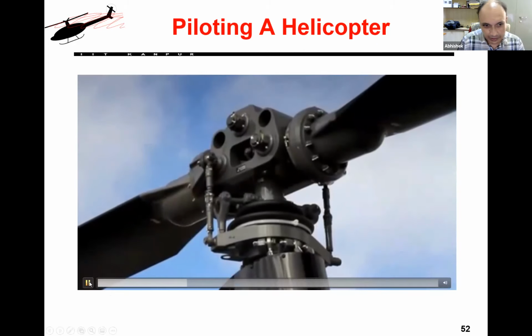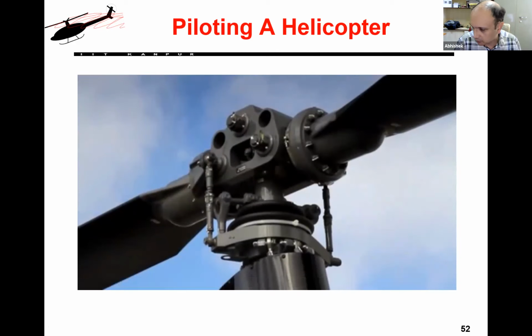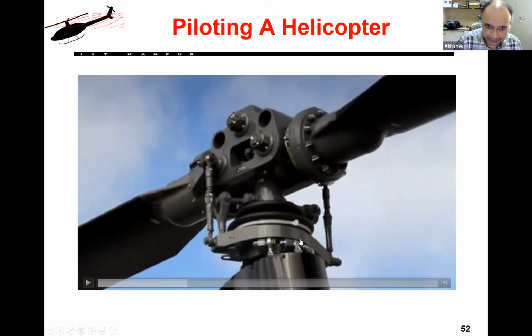Right. So this is the swash plate, and we'll look at another video of just the swash plate to see how it actually works. This actually has two parts. What you see here is the top part of the swash plate, which is the spinning part, and there is normally a non-spinning part.